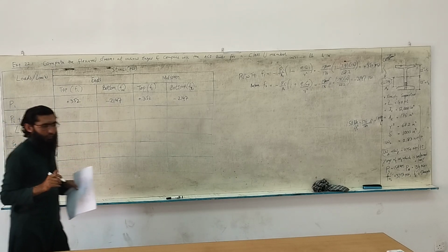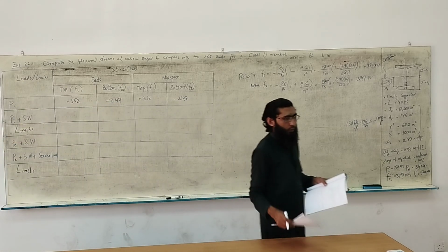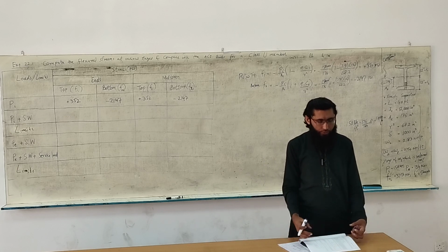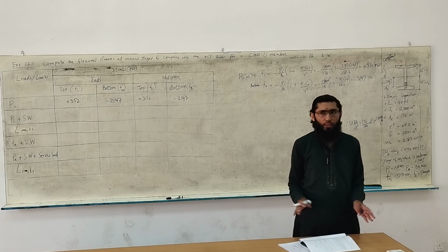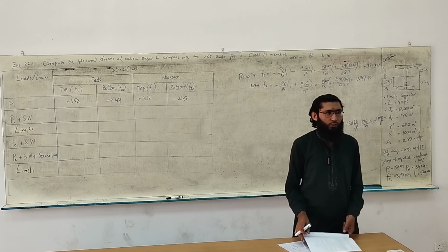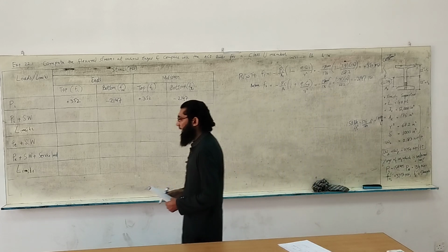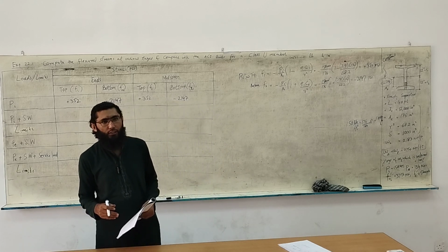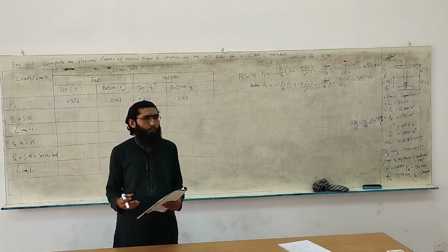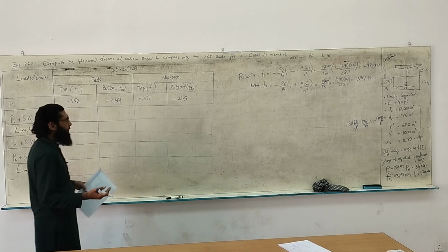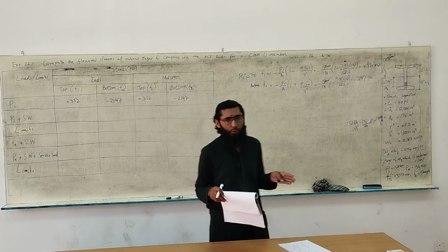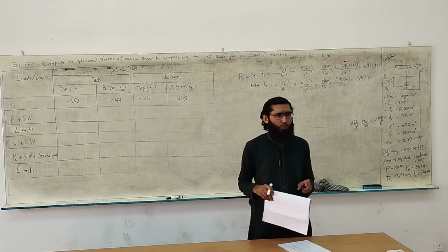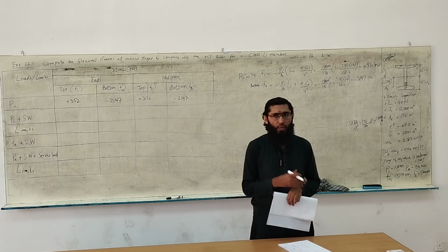But what happens is, as soon as you impart pre-stressing to the member, it just lifts up from the platform, and then self-weight is activated. So you need to account for the fact that self-weight will start acting as soon as you apply the initial pre-stress force. Now, that self-weight acts on a simply supported member. Will it produce any moment at the ends? No, it's a simply supported member.